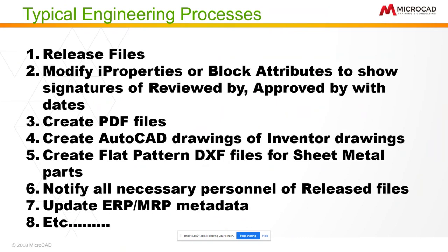That's a topic for another conversation at another time, definitely not today, but we will focus on how do you create AutoCAD drawings from Inventor drawings. And then a lot of times that's necessary if you're working with customers, vendors, suppliers. You're using Inventor, but they don't, so you want to give them a compatible file. Sheet metal, a lot of times you need to create DXF files for sheet metal parts, the flat patterns.